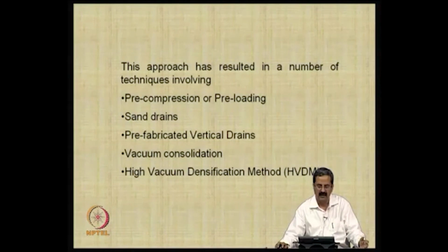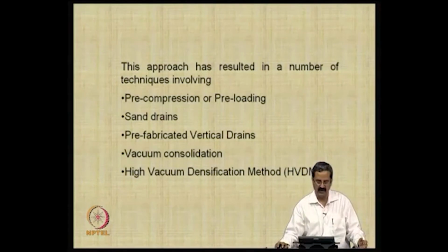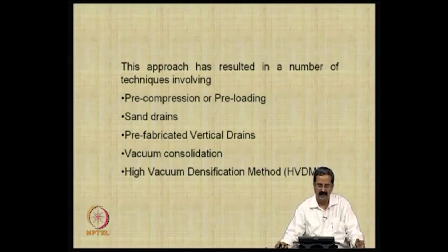The use of pre-compression or preloading has resulted in a number of techniques which have been used in the field. Some of the soils are normally consolidated. So, if you pre-compress, applying a higher load such that the later settlements are going to be less, it is called preloading.